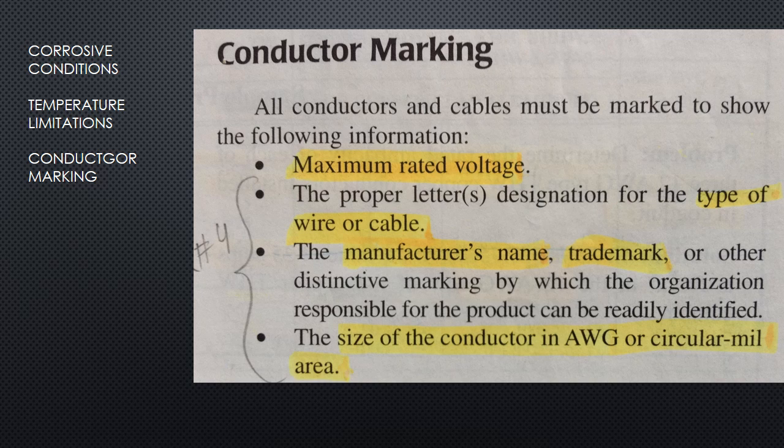Temperature limitation. Section 310.15(A)(3) of the code prohibits the use of any conductor in any manner where its operating temperature will be greater than that designed for its insulation type. Further, different conductors are not to be associated together in a way that would cause the limiting temperature of any conductor to be exceeded.